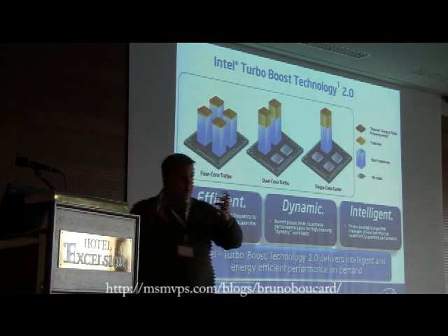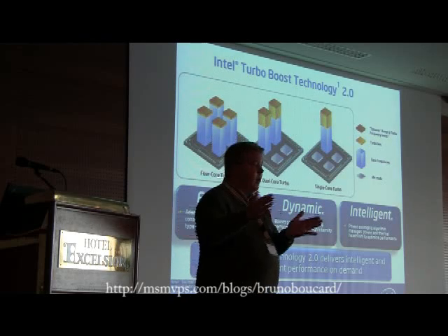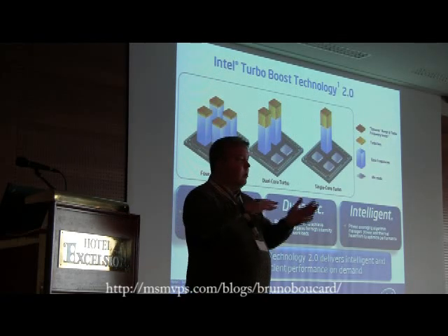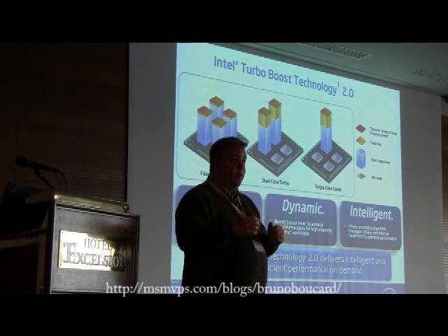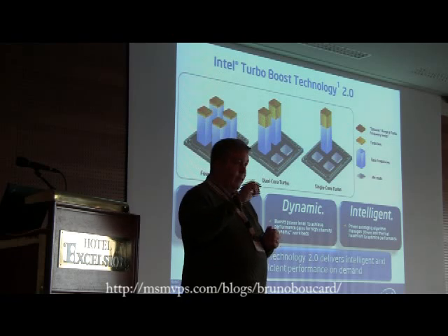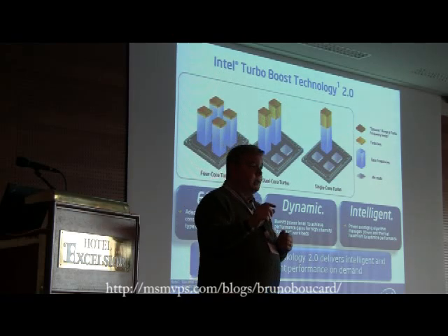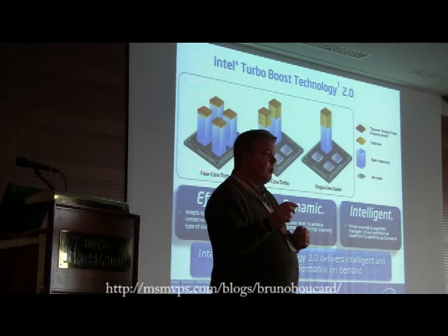Now here, to help solidify that, think about it. Back when we first started making multi-core processors, one of the reasons we said we could do multiple cores in the same package, in the same design, was because there's an exponential relationship between power and frequency. If you remember back then, we would say, you reduce the frequency by 15%, you halve the power output.